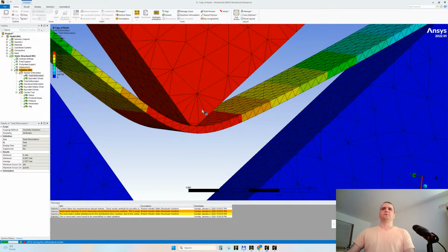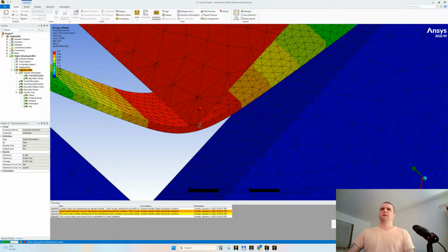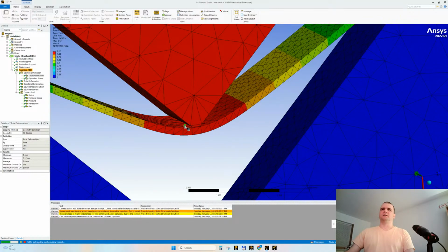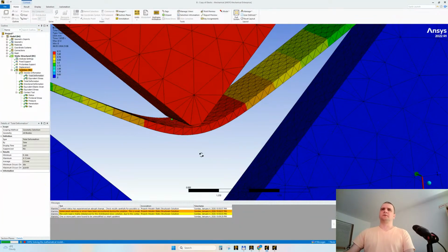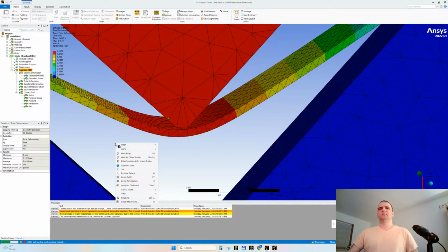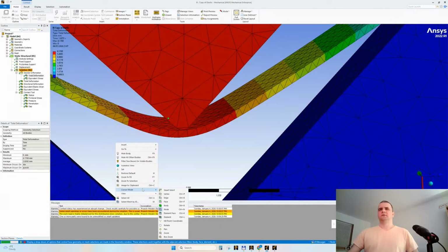But normally we should need, let's say, a much more refined mesh here, in order not to snap back, for these nodes not to jump into this mesh and stop the simulation. I think you will understand more soon.